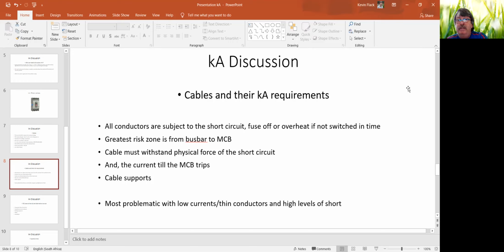And of course, at 5 amps, you could immediately go and say, well, that's a 1.5, even less maybe, squared millimeter cable connected to that. That would be the wrong approach. And that is kind of what I'm alluding to with this slide. The circuit breaker can trip and protect the cable, but the physical forces available on that cable could rip itself completely out of the terminations.